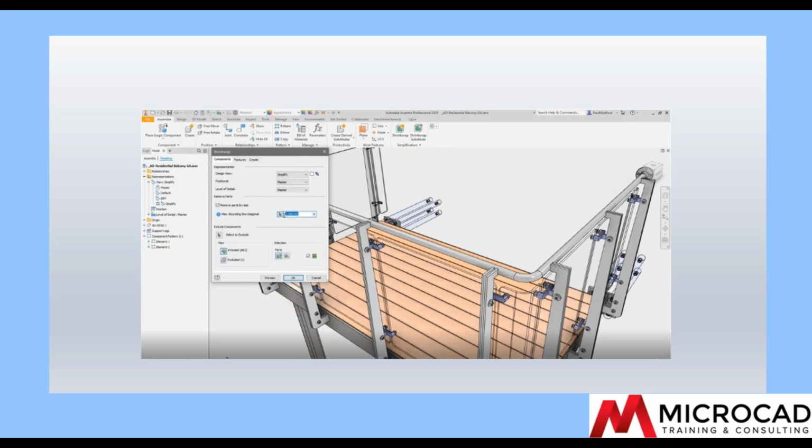Notice that the manufacturer's model is much more detailed than the architect's. This is because the manufacturer has to have everything needed to make the product, while the architect only needs the parts for visualization. The manufacturer may make some further changes, maybe because of an engineering calculation or to reduce costs. The manufacturing model is simplified and passed back to Revit as a Revit family for the architect to review.